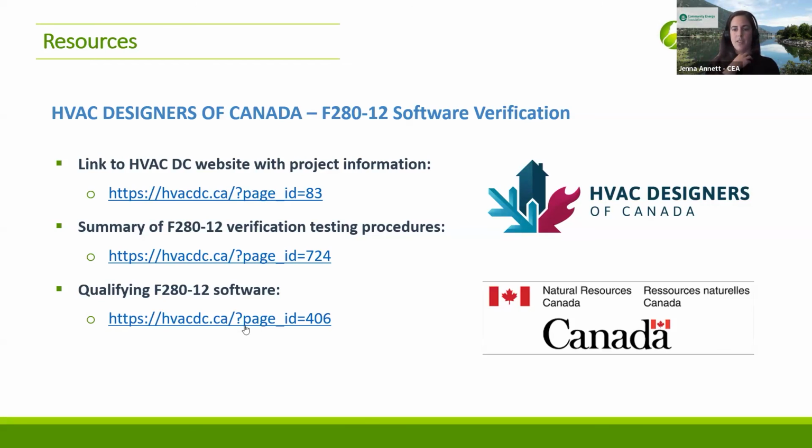And Mohammed just asked, after heat load calculations, when it comes to air source heat pump selection, are there any requirements or limitations for supplementary systems in CSA F280? How large supplementary systems can be? CSA F280, remember, is a heat loss, heat gain tool. It's not intended to influence your design decisions, right? How much supplemental heat, that's a design decision.